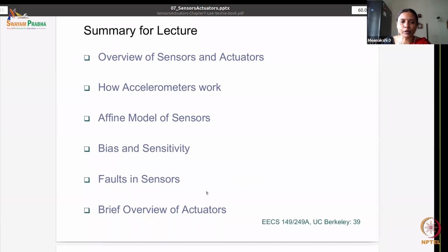So here is an example of a timed interrupt. My ISR gets registered and then a timer gets initialized. The timer keeps ticking its own time. And when the timer finishes, you process the interrupt. When you process the interrupt, you might be executing some task code. You come out of it, you update your tick and sample, which is the ISR, and then you go back to executing task code. So you can set up a timer on a particular processor. You can set up a timer on another kind of processor. These are examples for that. I'm skipping them in the interest of time.